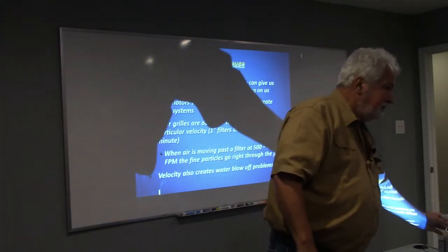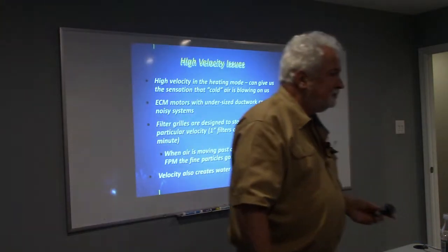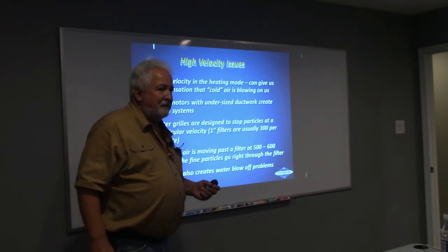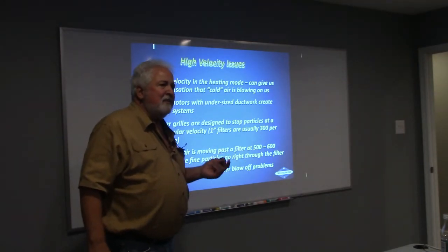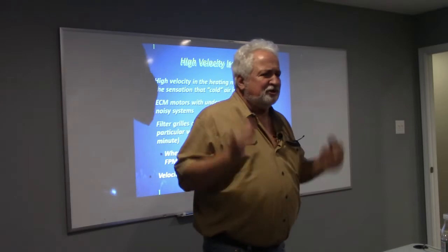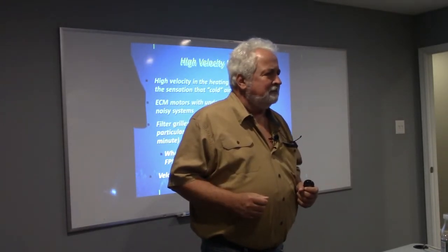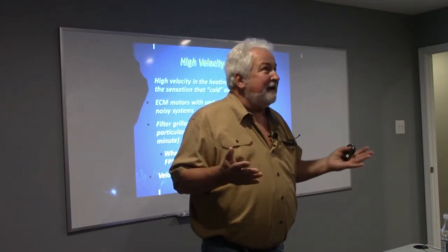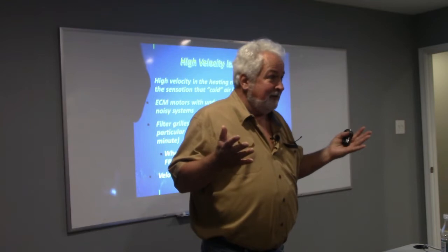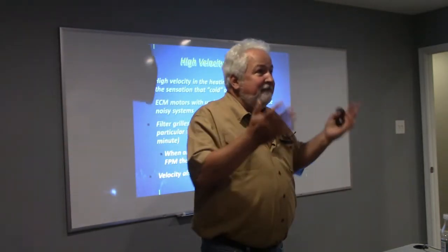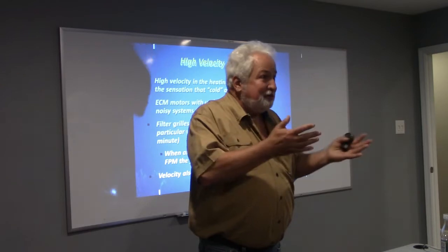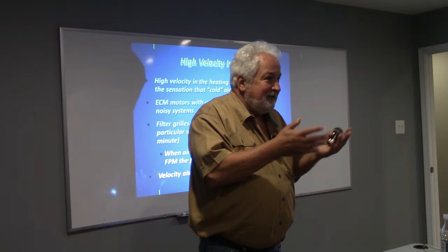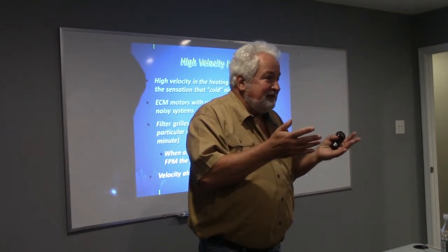What about y'all's superheat? What does it do? Drops it. It does. Yeah, that's what it does. If I'm not picking up the heat from the house, what makes that refrigerant super hot? The warm air passing across. Heat transfer. The heat from the house makes it boil. Makes it boil because it's evaporating. So if I can't get the heat from the house to go into that refrigerant, then the refrigerant didn't ever boil. It stays as a liquid.